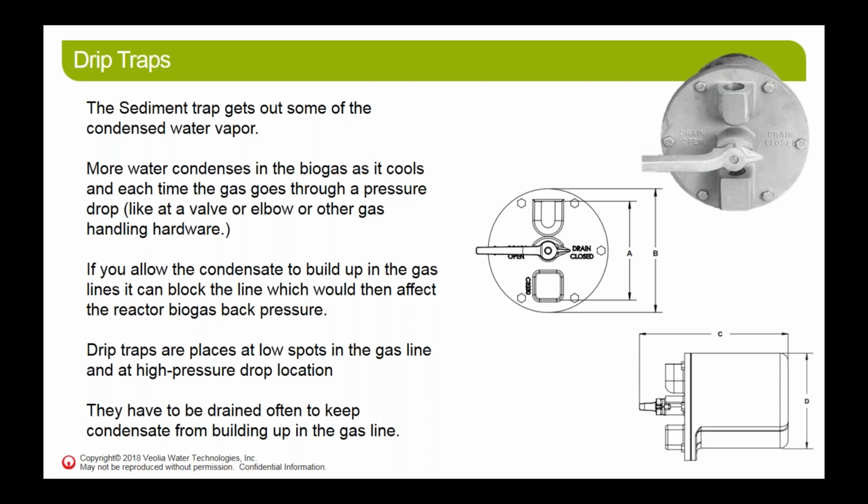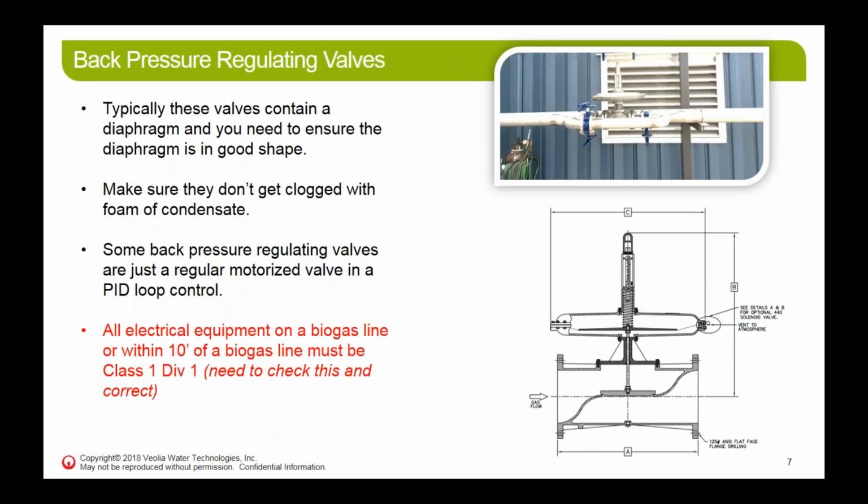And when you do that, you actually close the valve to the gas so there's no biogas coming out, which makes it a lot safer than just opening a line and draining it. So you're never exposed to the biogas with these types of valves. And you have to make sure that they're clean and drained regularly. The more gas you make, the more frequently you have to drain them, and the colder it is, the more frequently you have to drain them.